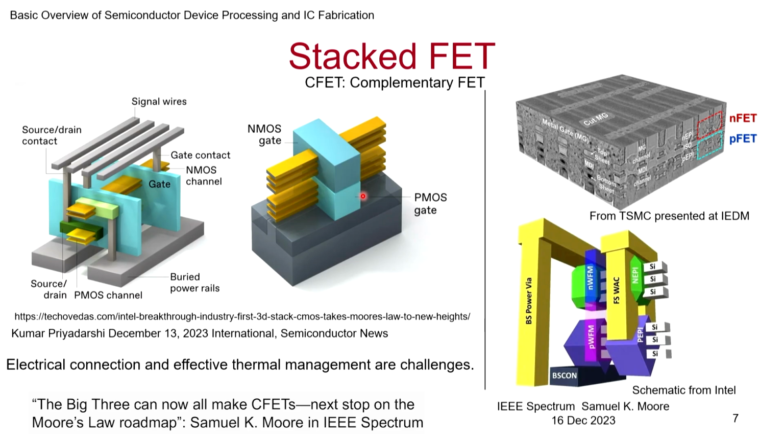Of course, strained N MOSFET and compressed P MOSFETs also have advantages. So actually, you can use strain also to change the mobility in these transistors. Now, you can see you have P MOSFET and N MOSFET. So essentially, it is like a NAND gate or NOR gate, depending on how you connect it, and they are built on top of each other. And today they are able to do this.